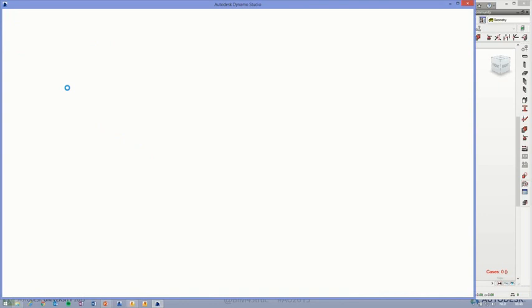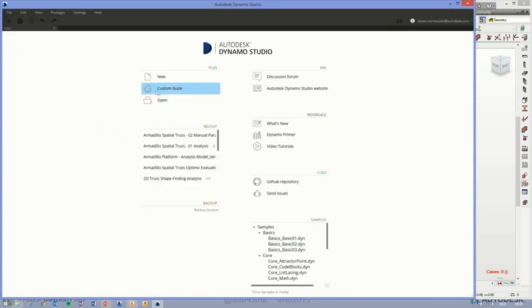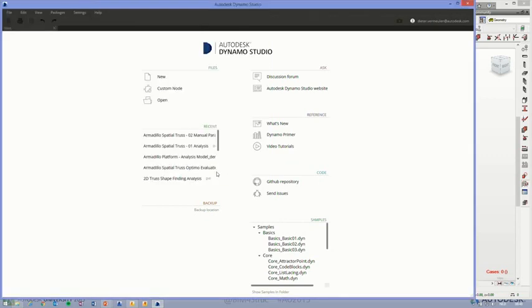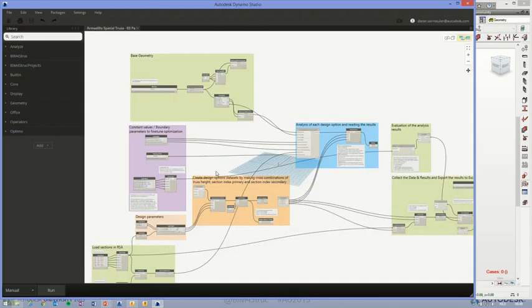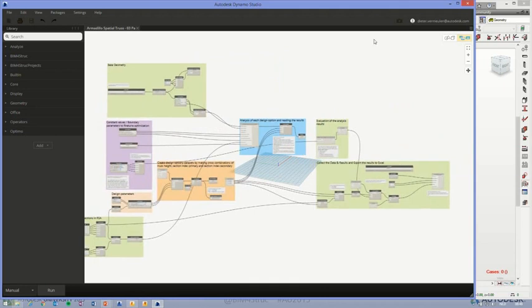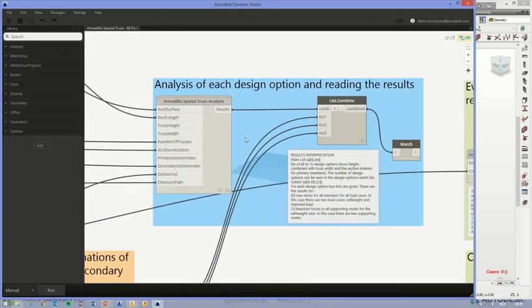It will check all these values and then return me some very nice information, which is what is the original weight, 5,400. What is the weight score? It's 12,000. That's not optimal. It's not a good solution. I can tell you already, at the end of this presentation, we will see that the weight score will be around about 11,000. Yeah? That's because some elements are over-designed,